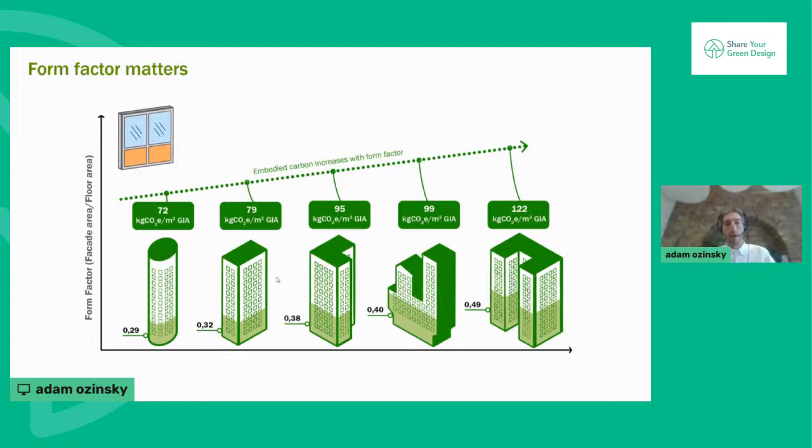didactic, what we did over here was we just took the same unitized curtain wall facade and mapped it across some fictitious buildings that had form factors ranging from about 30% to 50%. And you can see that there's more than 50% increase in embodied carbon. So that's exactly the same facade with the same materials, same design, same spec. You just have less material because you have less facade to wrap. So really something that we're pushing, and it works for cost, it works for heat loss. So this is one: good form factor. It's part of the good bones, good principles, and it's win-win-win.